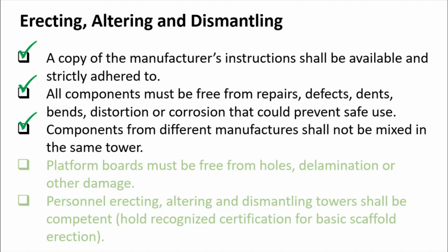So you get another component from a different manufacturer, which has less capacity or safe working load. Then what will happen to the existing mobile scaffold? It might collapse because of the lower safe working load of the bracing or the components. So never mix components of different manufacturers.